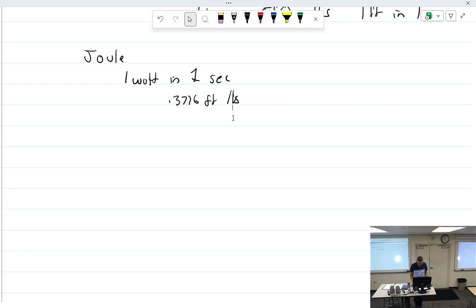So internal body resistance is only 300 ohms. 1 milliamp would be like licking a 9-volt battery, giving a little bit of tingling. 5 milliamps is accepted as the maximum harmless current. That is so little. That's what we're dealing with right now, right? It's just that our skin has so much resistance that if we did E equals I R on it, I don't remember what we're getting.